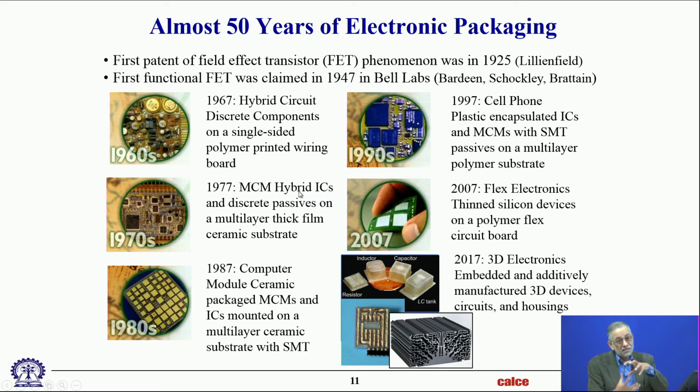Those were mostly, in those days, we weren't sure how well electronics would survive environments. We used to put them in hermetic packages, very expensive, either ceramic or metal cases. We put the electronics in there, seal them hermetically, and then mount them on circuit cards. Those were very expensive. Eventually, we just moved, as you well know, into plastics molded electronics to make things cheaper.